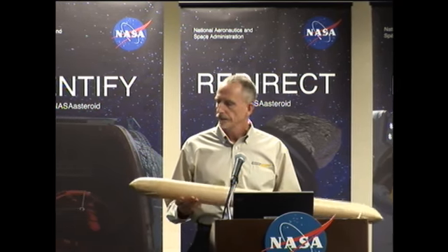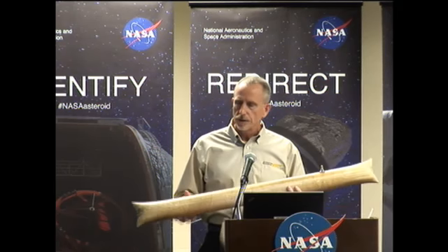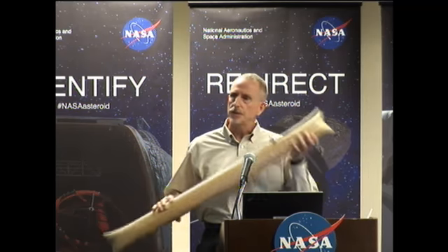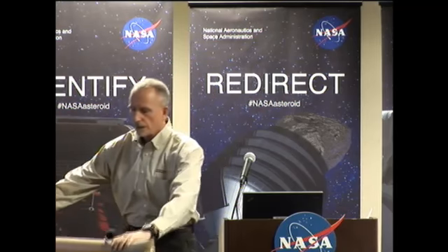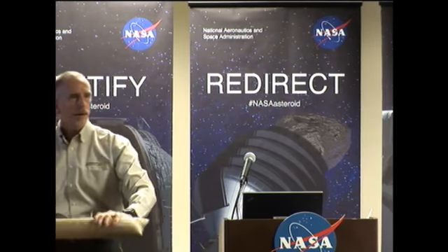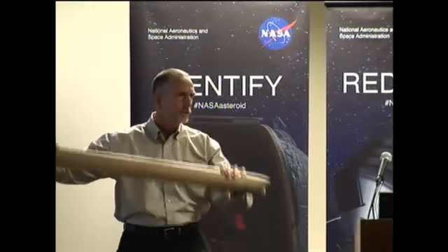And it has a gas barrier inside of it. And the unique feature is it has axial members, axial cords, axial straps. And that's what gives it the bending stiffness. This is probably inflated to 5 or 6 psi, and it's a very stiff structure. And I can buckle it, and it returns to its original position without any